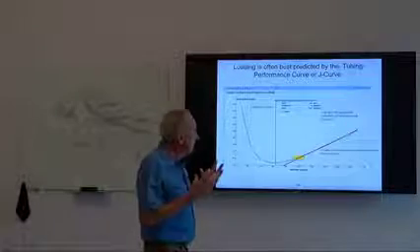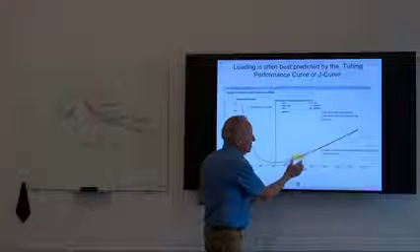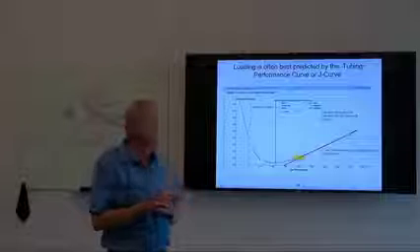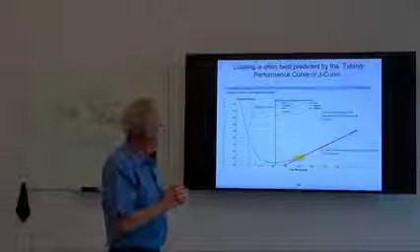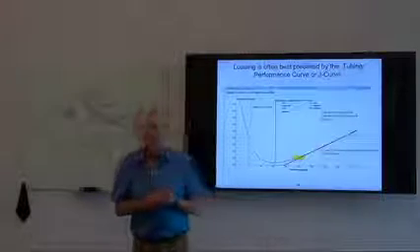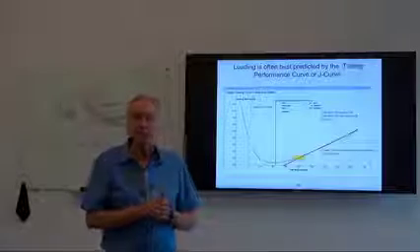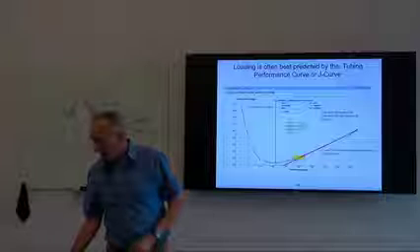So this tells us that there is a place here which is very highly predictable and has empirically proven out to be very, very accurate, provided your modeling is done well, that tells us when this liquid accumulation on the tubing wall at the end of tubing starts to begin, because that's where our liquid loading begins, at the end of tubing.